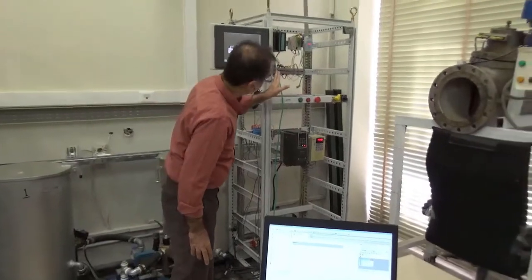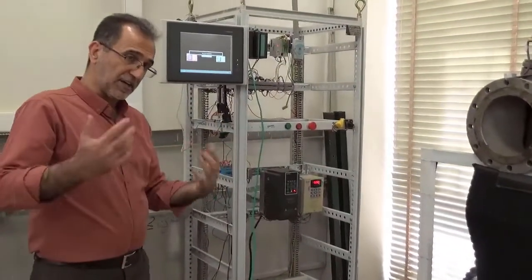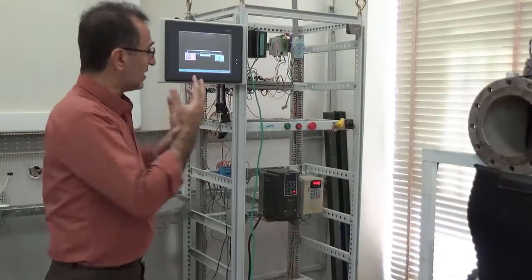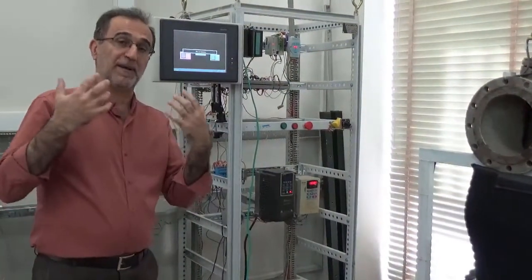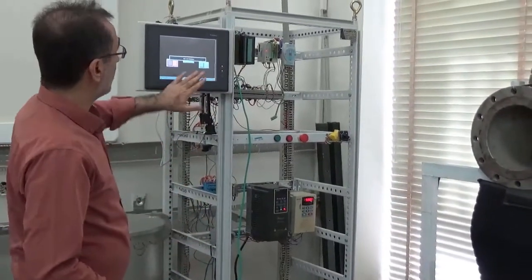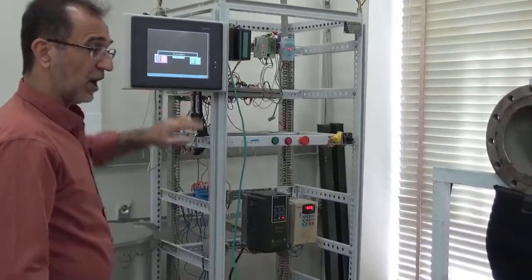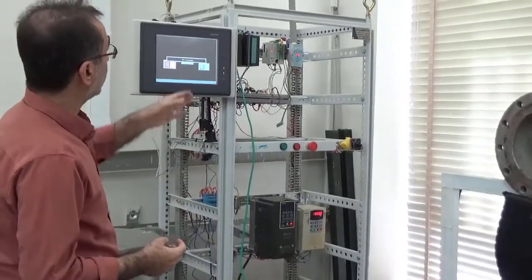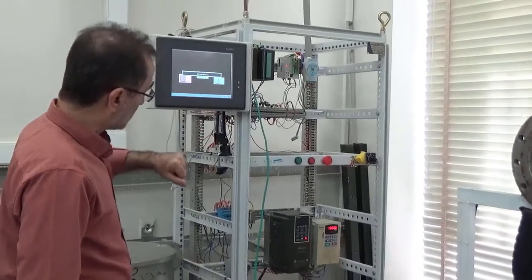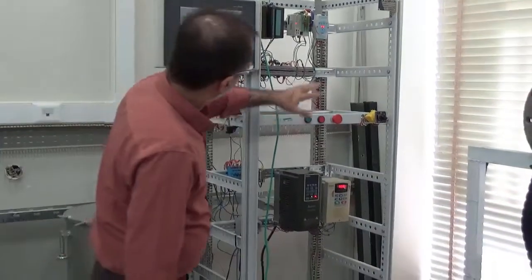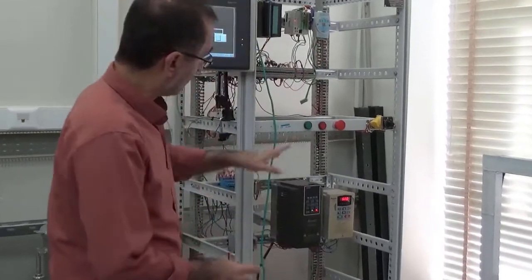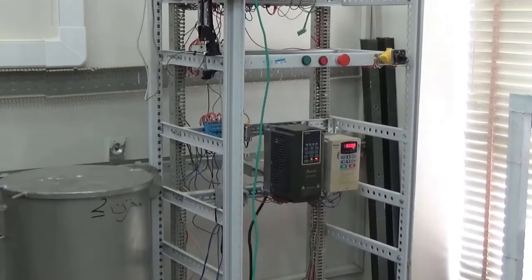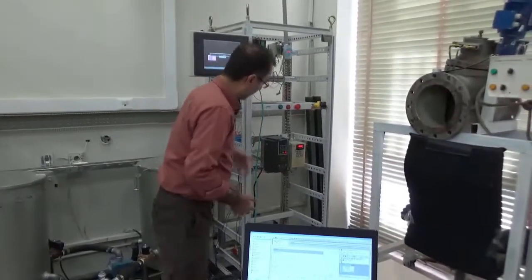Again, we use PLCs, and generally PLCs work for logic control, and the Siemens PLC can also implement PID control. And there is another HMI here. I showed you in the previous part the small one from the Delta company, and this is another HMI, but this is not active now. And these are the rest of the things. Again, the inverters control the speed of the pump for flow control, and the rest of the equipment.